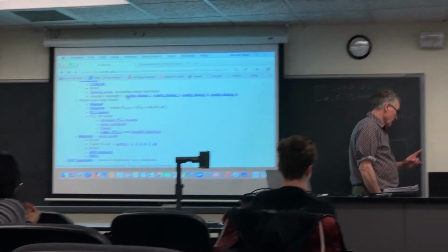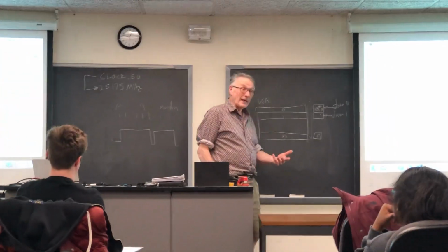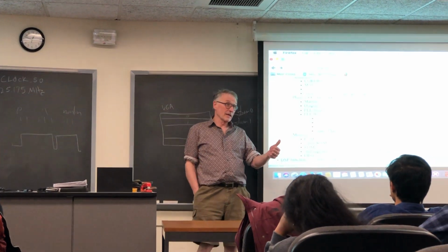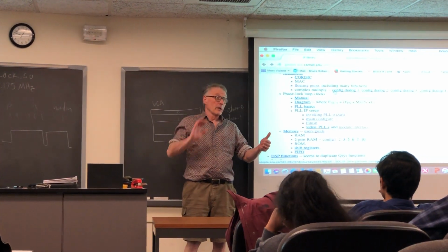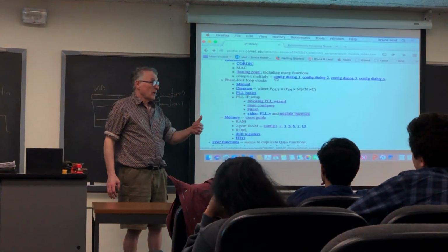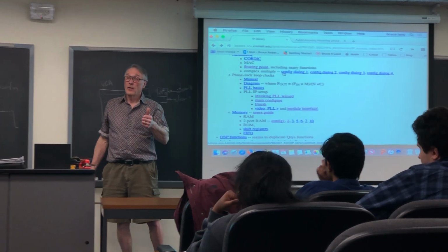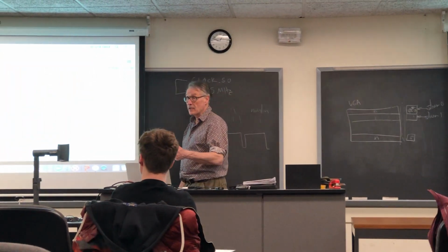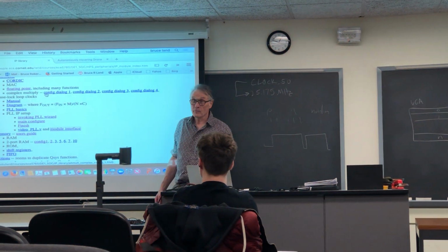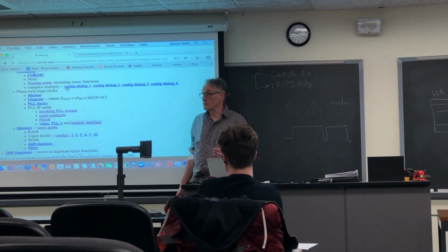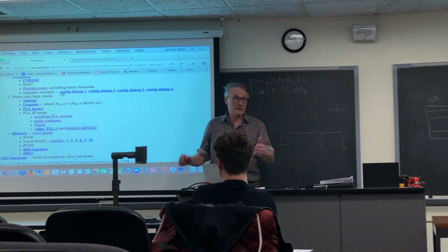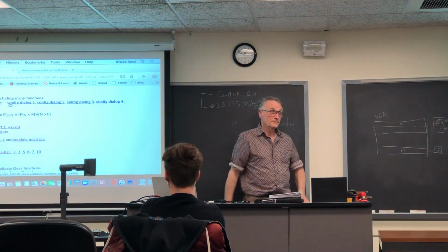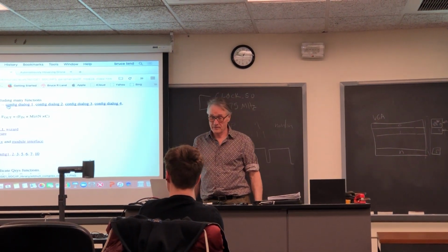The advantage of using a phase lock loop rather than just writing a clock divider is, first of all, the frequency is exact, and secondly, when you use a phase lock loop, the output clock appears on the clock distribution network instead of a logic line. The clock distribution network has much better timing characteristics and attempts to have all parts of the chip get the clock signal at the same time. So it's much easier to synchronize.